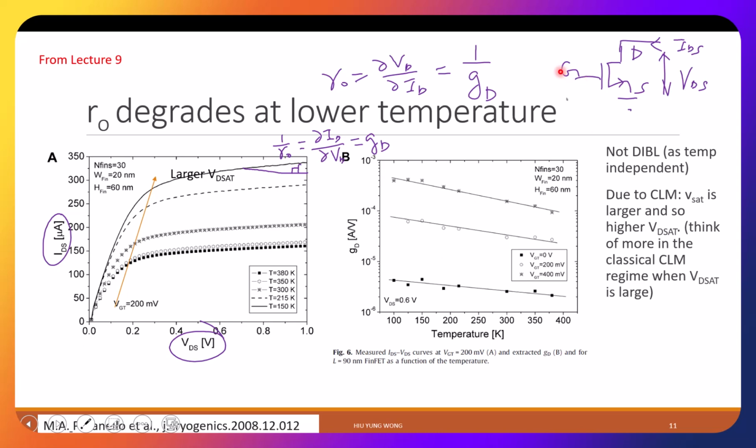No, we don't. When we do the gate, it's the Gm, how the gate changes the drain current. And the gate is supposed to be insulating, so we don't care about partial IG, VG. So for a transistor, we only care about how the gate voltage changes the output current, which is the transconductance, and how the output voltage changes the output current, which is the output conductance.